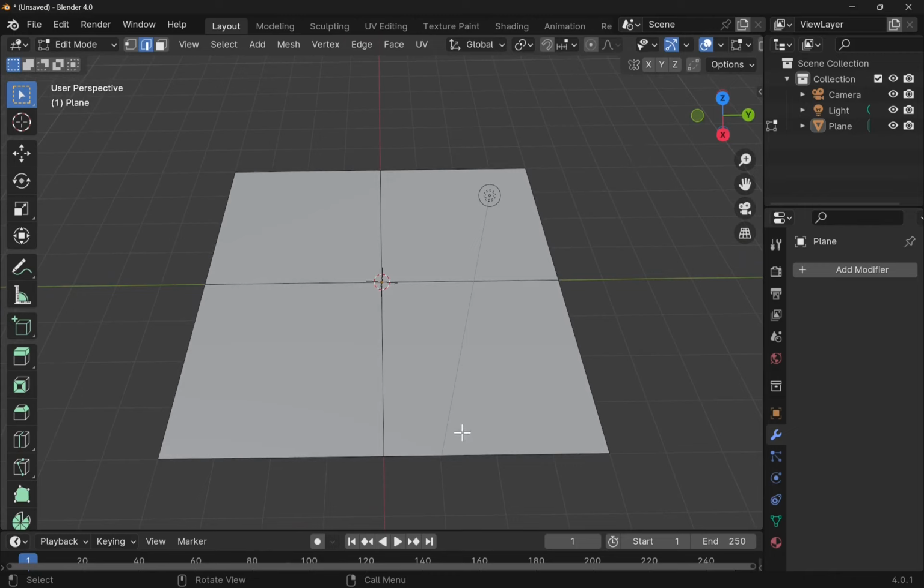So one here and one here, and also the same on the horizontal, making a square in the middle to support our hole. To do that, we need to select the loop cuts. We're on selection mode. And if I select one, you can see only one is selected. Now we could hold down Shift and select the other edge and do it this way. Or if we hold down Alt and Shift and select, you notice the edge is selected throughout that loop, and then select the other. So we've got those selected in there.